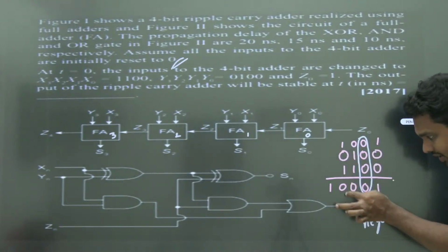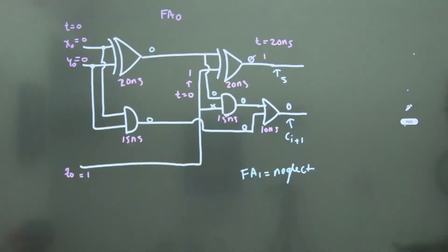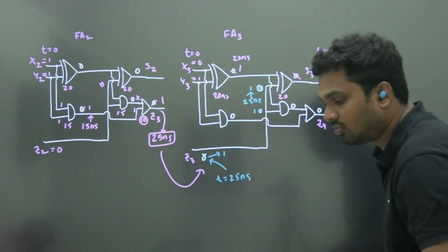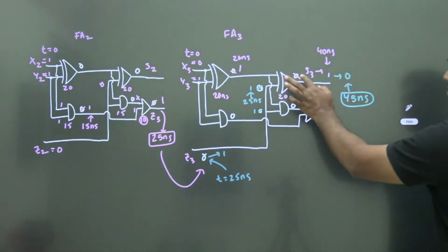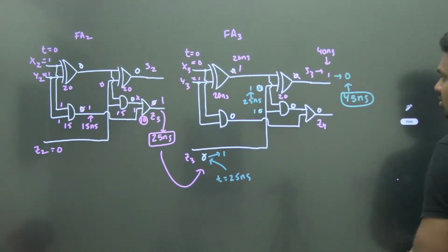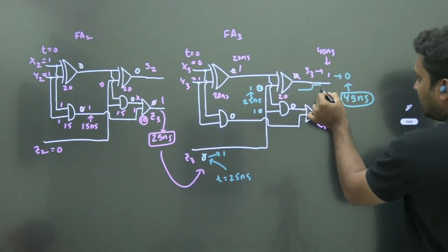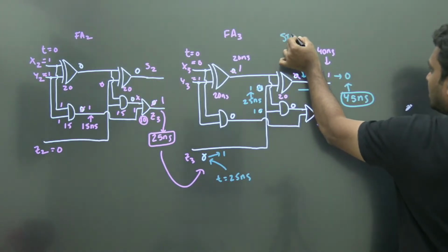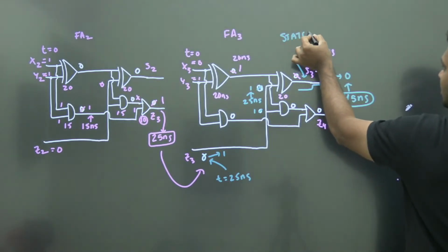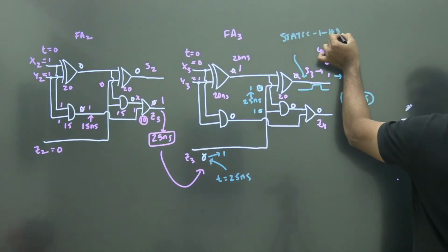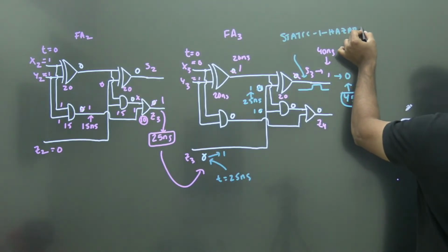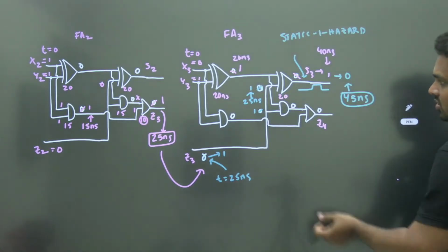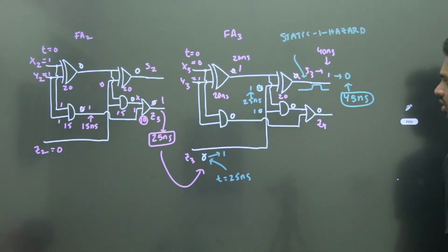But you cannot negate the time in this case because it is not stable. It is not stable. This is the condition what we call hazard. Even though it is initially 0, steady state में 0, बीच में it is giving you some 1 here. Na? This is called as hazard, static 1 hazard. That is, the output is in between changing to 1 and coming back, transient state आके 0 आ रहा है. Okay, because of the internal delays. Okay, छोड़ दो. Now come here.